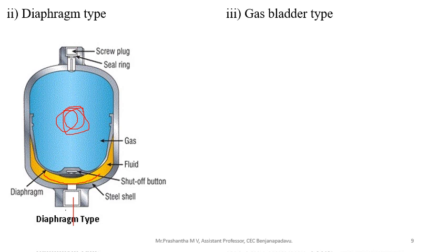When the pressurized liquid comes and acts on this flexible diaphragm, this gas is compressed. This gas is compressed, so pressure energy is created. So when this liquid comes and pushes this diaphragm up, the gas gets compressed, and the pressurized liquid is stored inside it. Wherever the fluid is required, this gas force is utilized to push out the liquid immediately or intermittently.